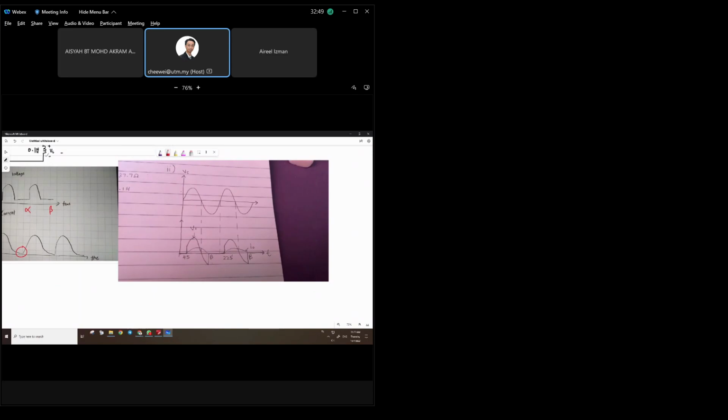This is VS, a sine wave, the input. Correct? Then there is pi and 2 pi. What is this? Alpha equals 45 degrees. And then you have pi. And then you have beta, which is the stopping of the current. This is current. This is voltage. Okay.